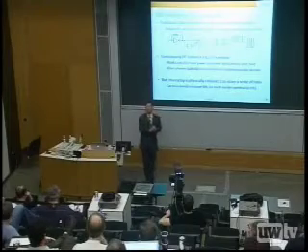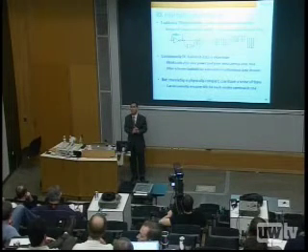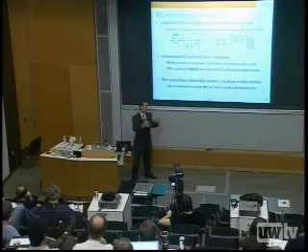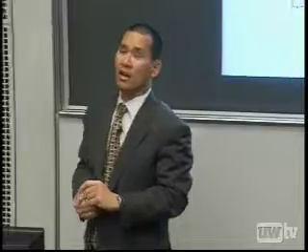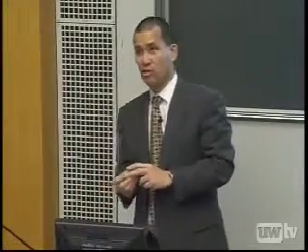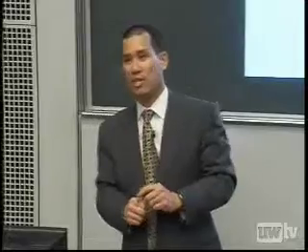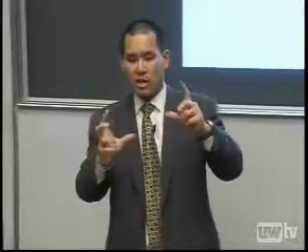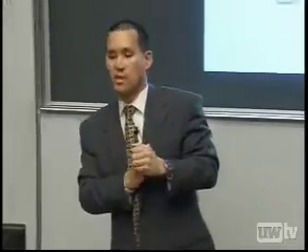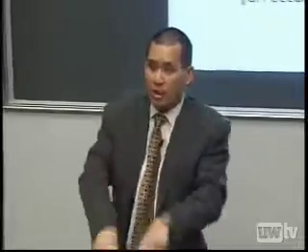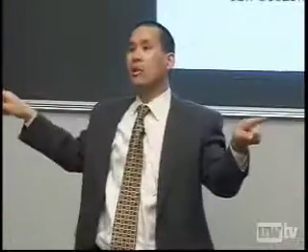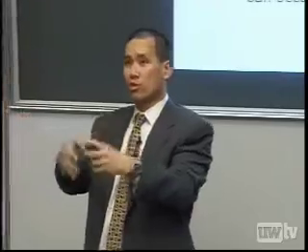So you talk about the capacitive coupling. Can you also do inductive coupling? Right, I'm repeating the question: can we do inductive coupling in addition to capacitive coupling? The answer is you certainly can. A good friend of mine, Professor Kuroda at Keio University in Japan, has been doing inductive coupling for quite a while. Inductive coupling is just like capacitive coupling, except it uses magnetic fields. They're both pretty good technologies. I believe capacitive coupling gives you better noise performance because inductive coupling loops tend to be big. You tend to have magnetic fields that circle what you've got, which means you better separate your channels by quite a bit, or they'll talk to each other.